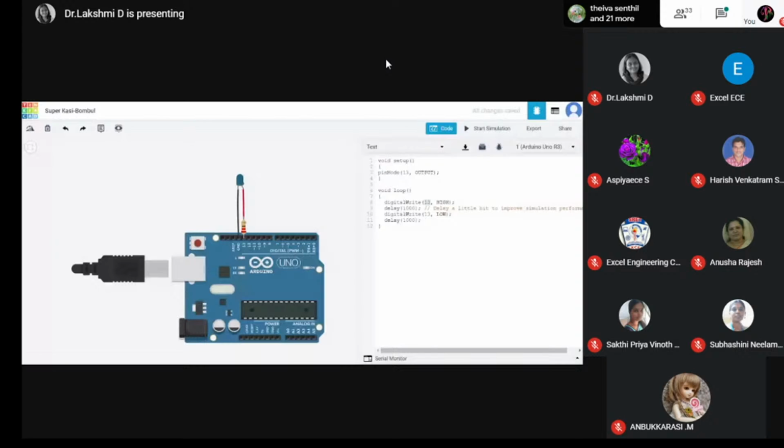You need to give the pin numbers here. Next, there is looping; it should always have looping. This looping is the action that will be done continuously. That is what IoT is all about: we need to have a looping control. So digitalWrite 10: first I want to make this HIGH. Pin 10 is attached to the red LED. When pin 10 becomes HIGH, I need to put all the others LOW. If you wish, you can change the logic. I may want to blink all 3 at a time, or turn off all 3 at a time. The choice is yours; you do a game, whichever game you want.